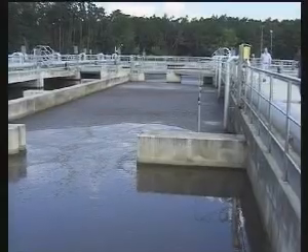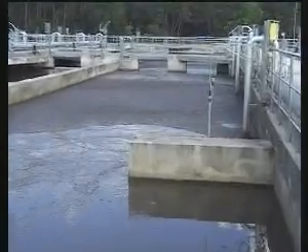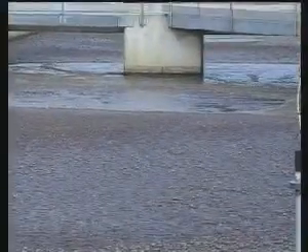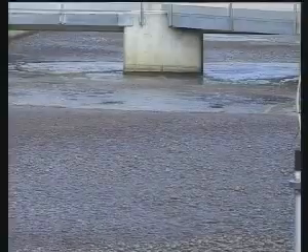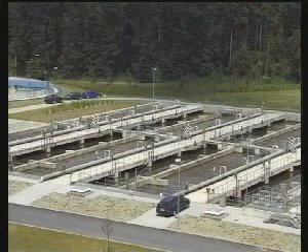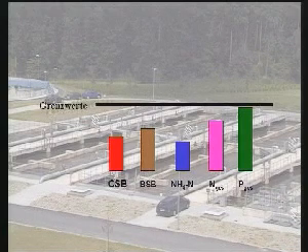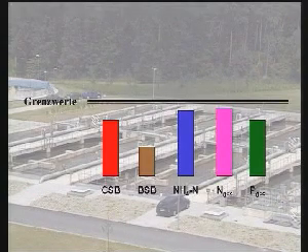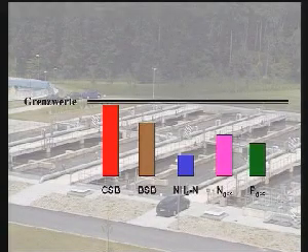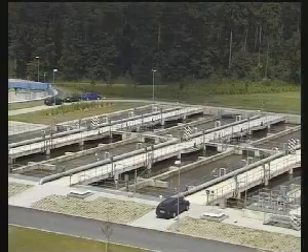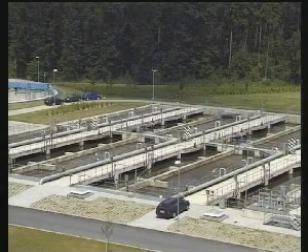Most wastewater is purified at our sewage treatment plants by the use of the activated sludge process. This process enables the biological removal of carbon and nutrient compounds from the wastewater. The permissible pollutant limits for the discharge of wastewater from a municipal sewage plant into receiving water are laid down by law as a function of the size of construction of the plant. European legislators demand reliable adherence to these limits under all inflow conditions and at all times.